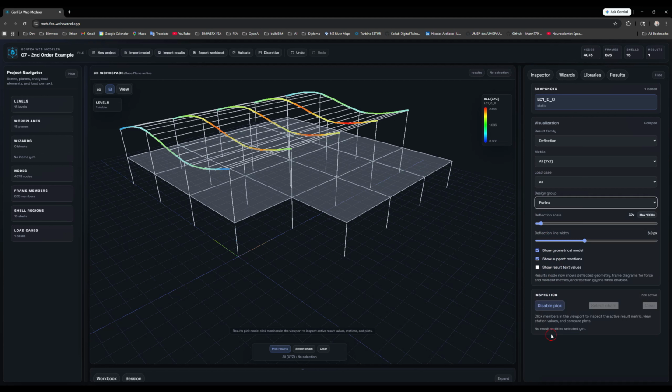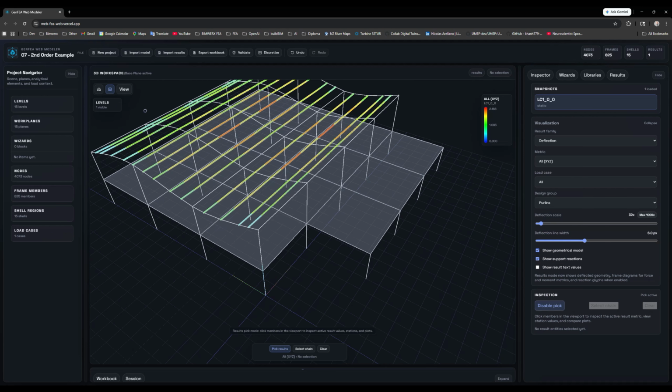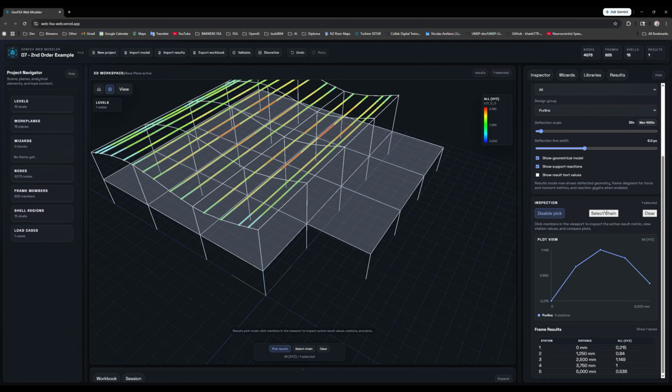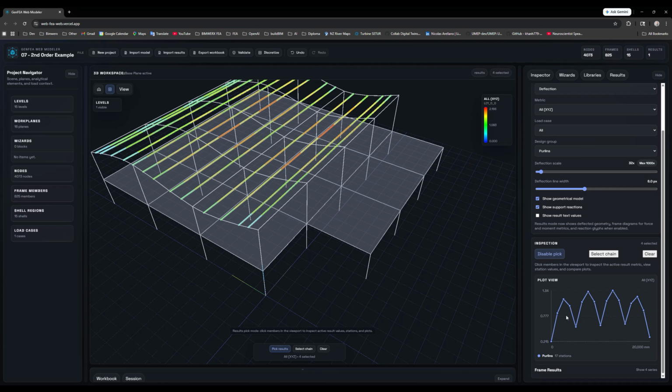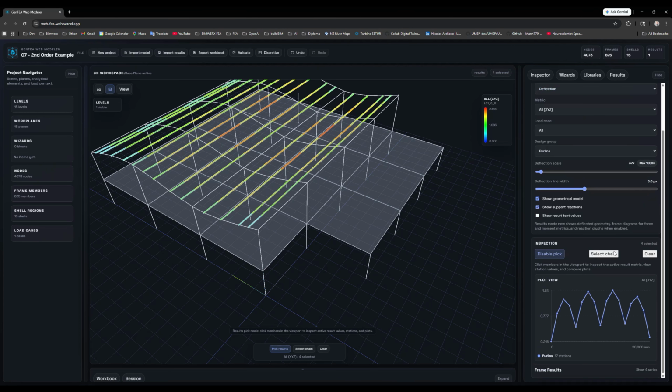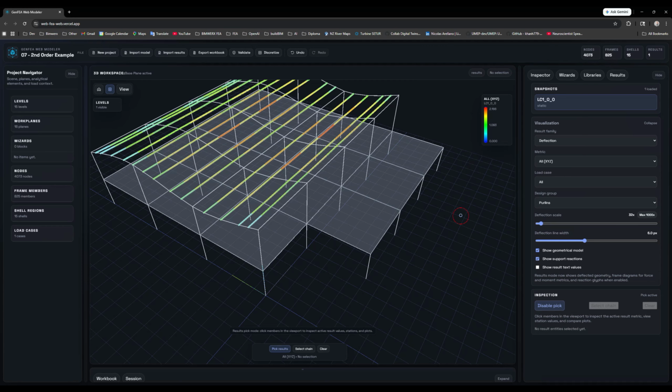And then, of course, if we switch to the purlins here and we use the selector, it will then allow us to view that plot view. And there's the select chain button, which means we can now also select the connected elements that belong to that same discretized master element. And then if we want to drill deeper into the various segments, we can also do that.